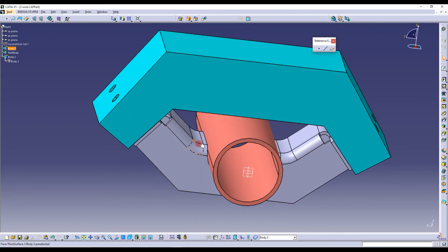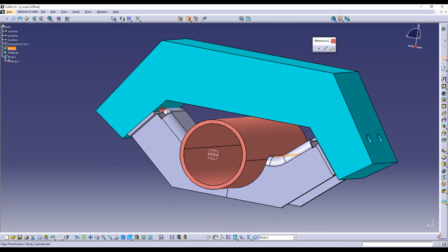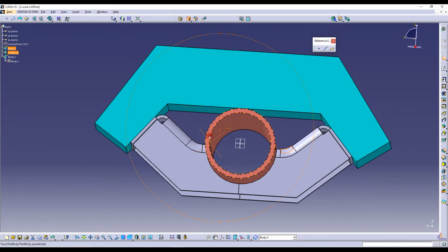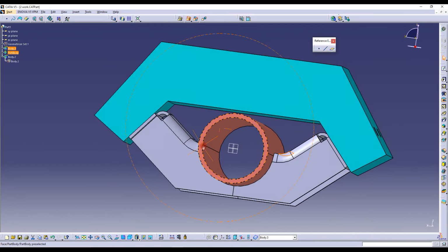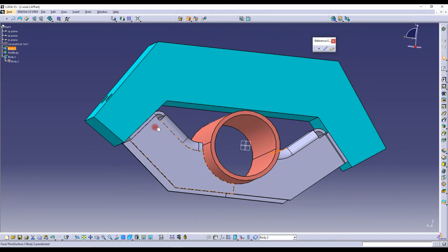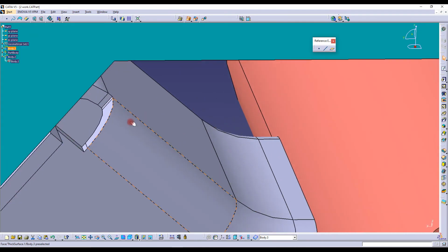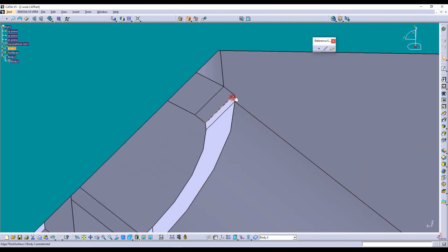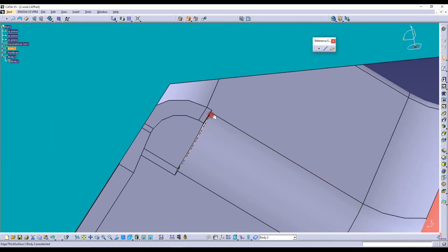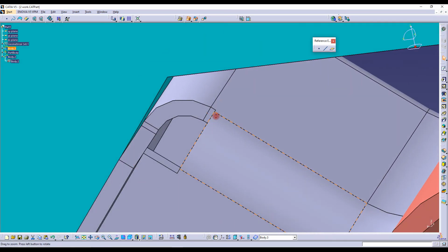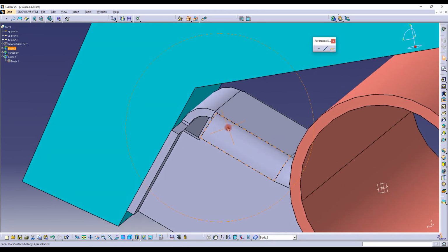So it is having a form here because of these two fillets as it is like this, and it is also having the bending area which is over here. So it is a combination of both which gives it its functionality to be welded over here as well as being bolted over here for this kind of a geometry. So here there is a very less clearance between the fillet and this edge. It can be increased for better bendability and formability, but this is just a reference design to show the design process.